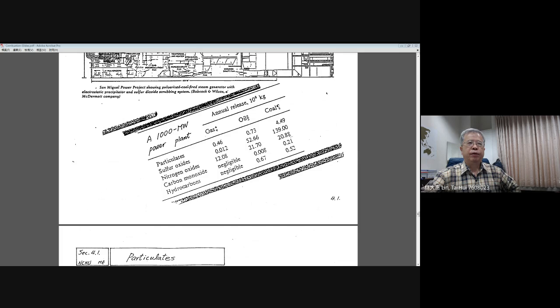the so-called fuel NOx, from the nitrogen content in the coal. But with natural gas, when you burn it, the thermal NOx comes from the high temperature. And the oil just adds these two effects together.